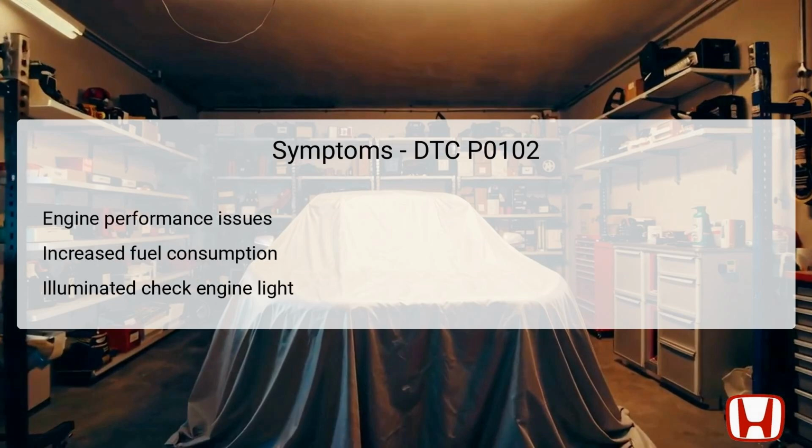When DTC P0102 is triggered, drivers may experience several noticeable symptoms. Engine performance issues can arise, leading to poor acceleration, rough idling, or even stalling. Such symptoms occur as the engine management system is deprived of accurate information regarding airflow, causing inefficient fuel-air mixtures.